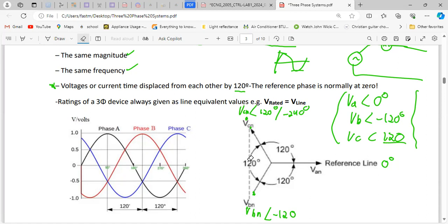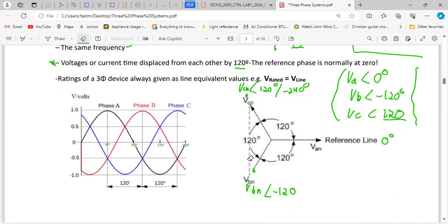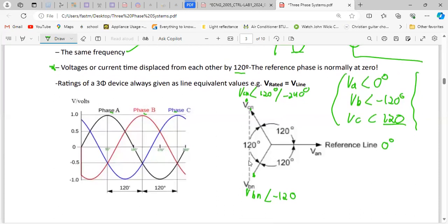The phases or the currents, depending on what configuration you're in, are 120 degrees away from each other, right? So this diagram is what I want to draw. So you notice that the magnitudes, or the peak, is a balanced system, right? So you see now the peak is the same for each phase, right? And it's a three-phase system, so the three single-phase transformers together supply a three-phase supply, right? So this is how it will look on a voltage-time or voltage-angle graph, right?